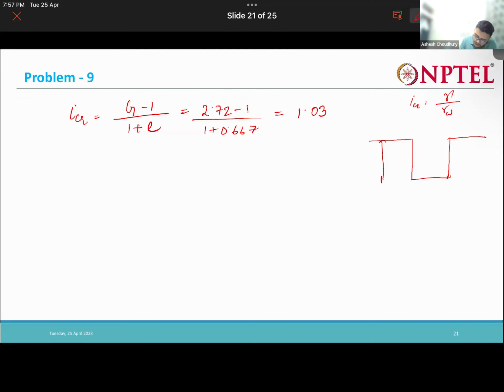Now say you are making an excavation. So due to the excavation, you pull out the water from here. So what will happen? Water will try to enter from here, right? From all sides, water will try to enter. So this will put an upward seepage force. Due to this seepage force, the possibility is that there will be quicksand. So we found out that if the hydraulic gradient is greater than or equal to 1.03, this quicksand condition will occur. Right.